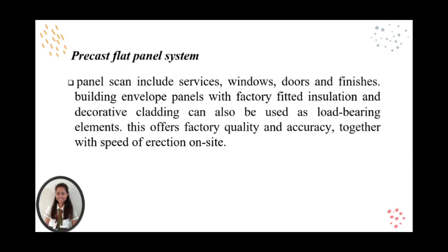They can also include features such as decorative wall finishes, fitted insulation, and so on. Some types can be used as load-bearing panels in cross-wall construction applications. Precast flat panel system can reduce on-site waste and ongoing maintenance, but they can be difficult to transport and handle. Using the precast flat panel construction technique may shorten construction project completion times.